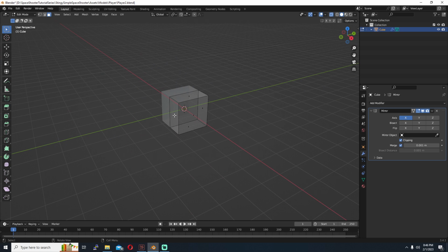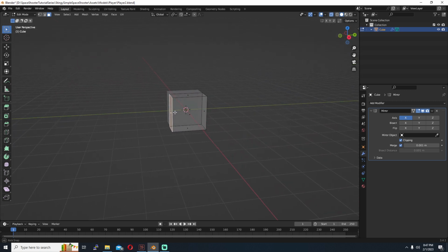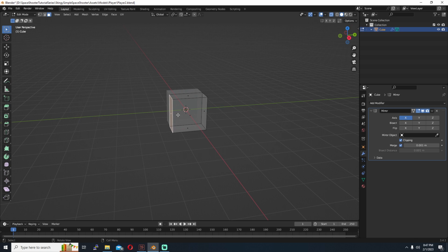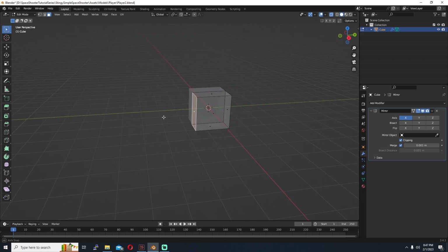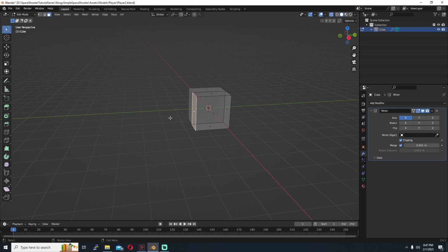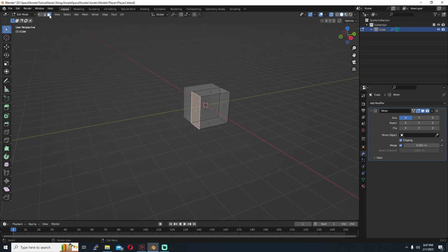I'm going to start by clicking on the very front of our spaceship, and I'm going for a fighter pilot sort of looking spaceship. So I'm going to select the front, and I'm going to start making the nose of the spaceship. So with this front face selected, and again, to select faces, I came up here to select mode and made sure it's this third icon for selecting faces.